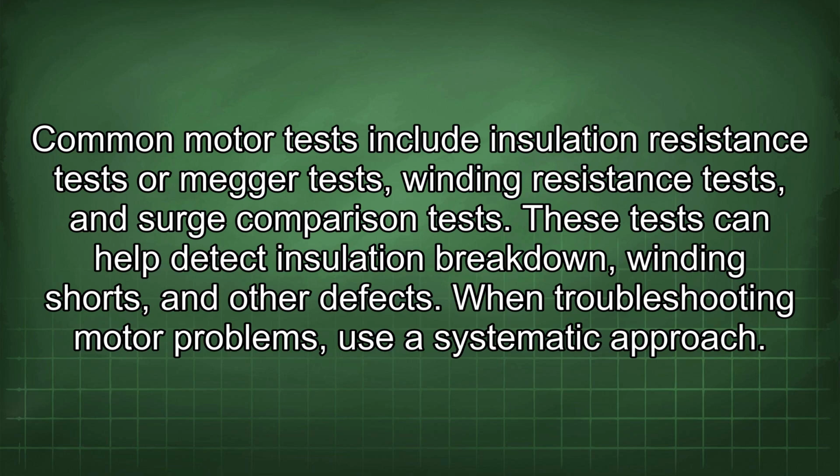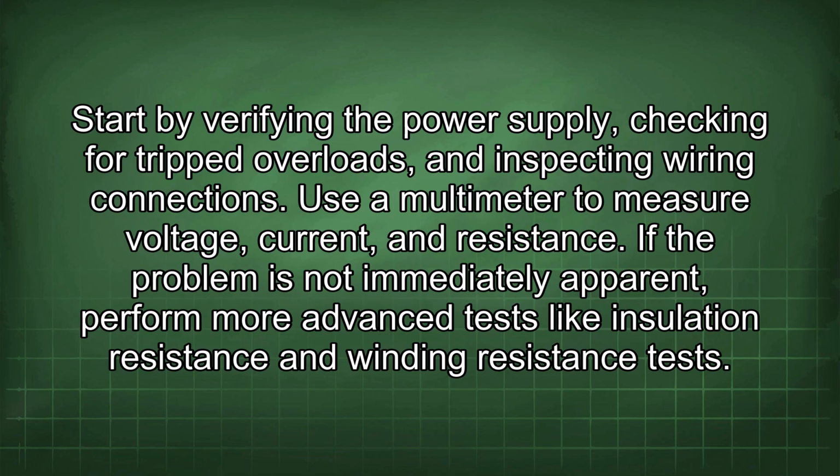When troubleshooting motor problems, use a systematic approach. Start by verifying the power supply, checking for tripped overloads, and inspecting wiring connections. Use a multimeter to measure voltage, current, and resistance. If the problem is not immediately apparent, perform more advanced tests like insulation resistance and winding resistance tests.